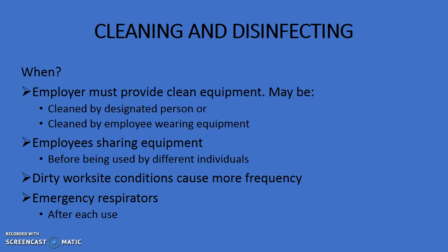Respirators must be cleaned as often as necessary to prevent them from becoming unsanitary. Some employers may use a centralized operation where employees receive respirators that have been cleaned and disinfected by other employees assigned to this task. But they may also require that each respirator wearer be responsible for cleaning and maintaining his or her own equipment. In addition, respirators worn by more than one employee must be cleaned and disinfected before being worn by a different employee.